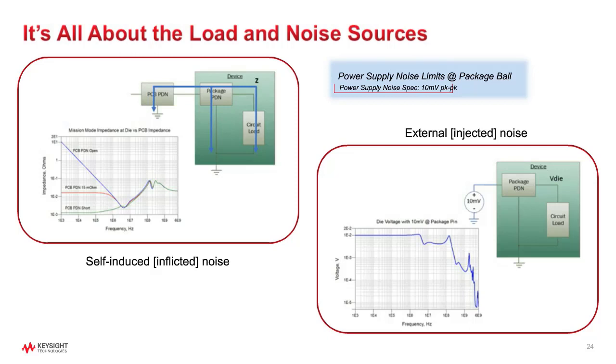However, if a package die model is available, then it can be used to estimate how much capacitance is internal to the package die, and from this capacitance, infer an estimated maximum amount of inductance for the PCB power delivery network that the package die capacitance can compensate for. This is done by using the simple capacitor estimating equation for flat impedance in reverse, and this time solving for the inductance that the package die C can compensate for to get a flat impedance.